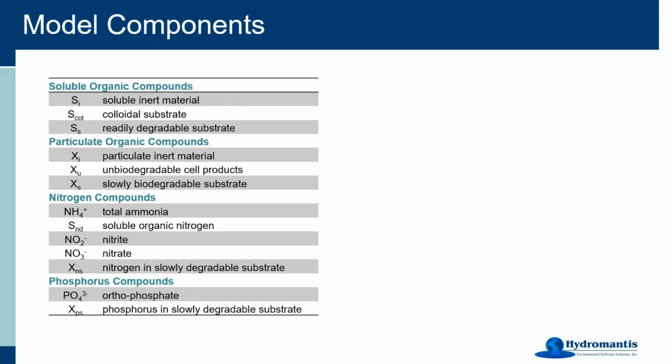Again, even though our main focus is physicochemical treatment in water treatment plant systems, we still sometimes encounter, for example, ammonia or nitrates coming into your system. In those situations, you want to do some biofiltration, or you want to utilize some of the biological processes. To address that, we allow you to have some inputs with respect to the organic carbon coming into the plant, and some of the structure we have borrowed from how we model it in the wastewater treatment plant.